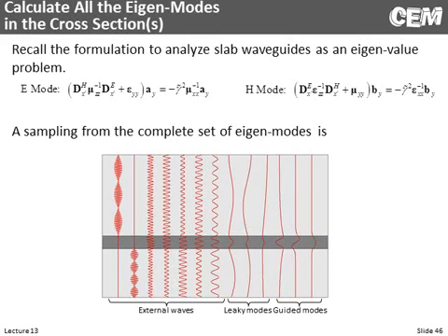So recall when we had our waveguide lecture, we learned how to analyze slab waveguides. Well, when we extracted those two regions on the previous slide, and we said they're kind of like our reflection transmission regions again, those are slab waveguides. It's a one-dimensional model with a core somewhere in the middle of it. So we go back to those codes and we analyze those waveguides and we calculate all of the possible modes that can exist in those windows.